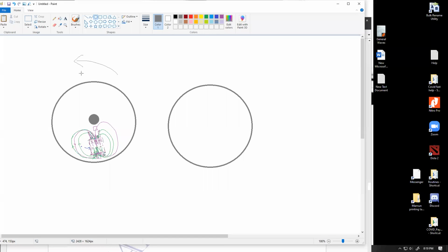If we apply the entire thing under a single magnet, the electrons will be pushed to the same side. For example, if we had a really large north pole and south pole applied like this, in that scenario we would simply have a very high negative voltage on the periphery and a very high positive voltage at the center, and it would remain at that voltage difference throughout its duration. We would not have any eddy current because the electrons would not have any return path. To achieve eddy current, you need certain locations under the magnetic field effect and certain locations free of the magnetic field effect, so that those free locations can work as the return path of the current, which completes the circuit within the metal disk.